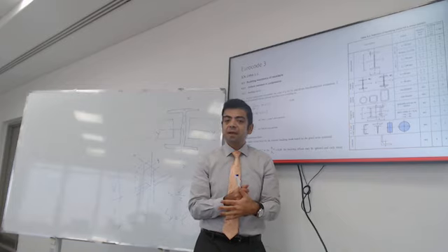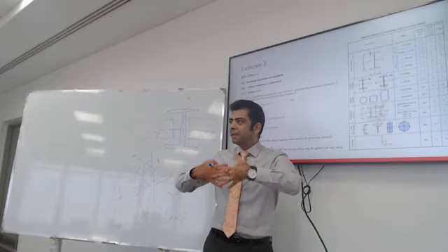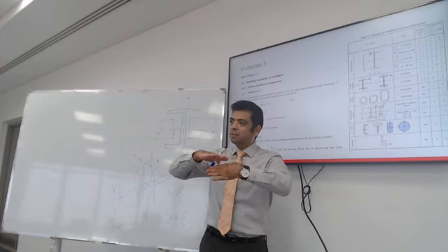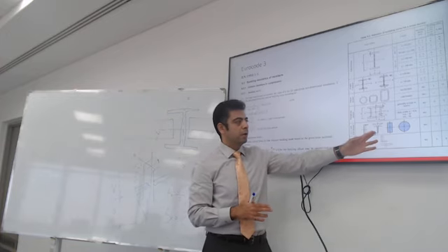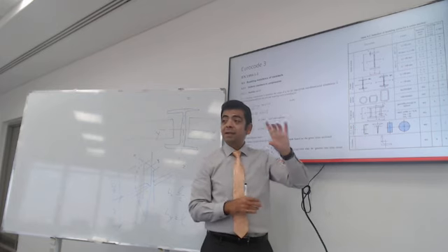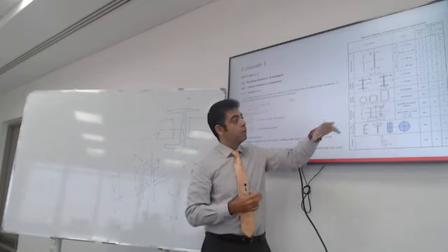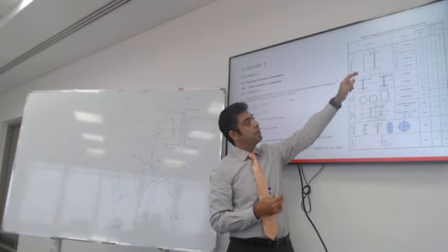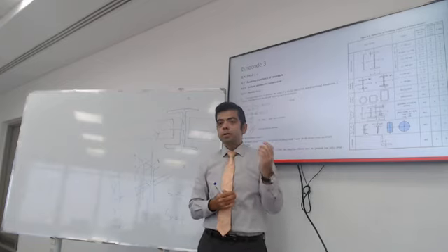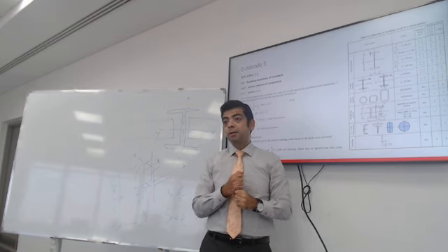So when you're designing a light beam, where there isn't a big load on it, it's mainly flexure and it's braced on the top, maybe you can resort to these light sections. When you're developing a column, maybe you want to do a closed section. The I sections work as well. You just need to follow the equations to make sure that you have the correct buckling capacity.